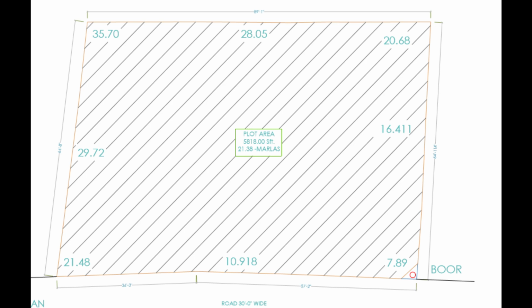For this problem, mostly people excavate the site area totally, but the excavation budget is very high if you excavate the 35.70 feet height, and then where will you deposit the remaining soil? So for this we had an idea to construct two different retaining walls on the roadside and the different side near the bore.